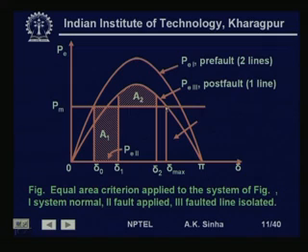That is up to this point delta max, which will be equal to pi minus this angle that we have. So, pi minus this angle will give me this delta max, and that is the maximum point up to which we can work. So, that will give me the critical angle.